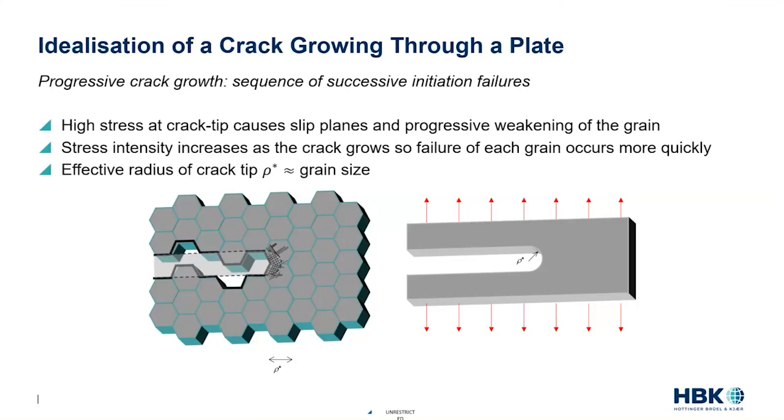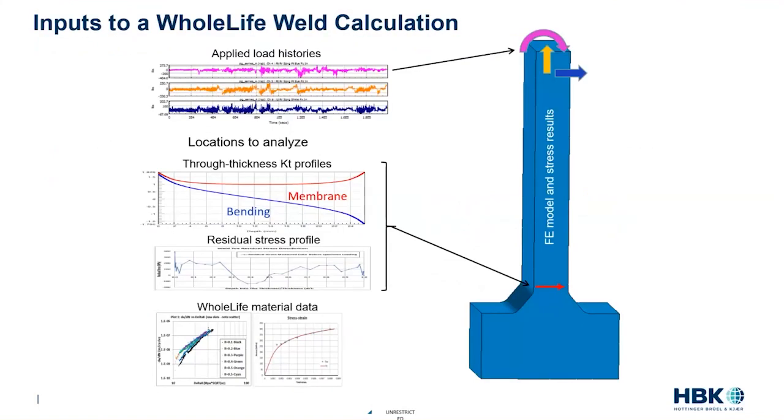The other key aspect of this is the starting point is basically predetermined by the calculation, is this radius of the grain. And so that's our starting point. So it eliminates a lot of the unknowns about what my starting crack size is. It literally is based on the microstructure. And what we've done is taken this basic crack growth approach and have integrated it directly into a final solution.